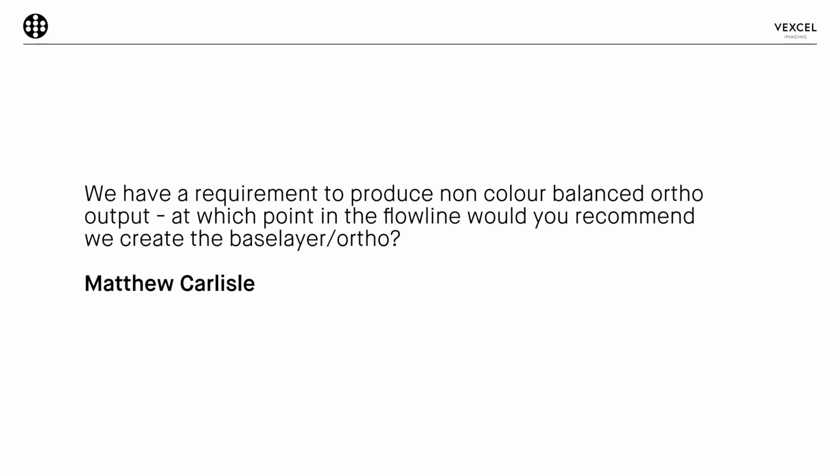So going for the first one, color balanced orthophoto, this is like the default path to continue in the software. And then for the non-color balanced orthophoto, we recommend that you take the radiometric settings from an early stage in the workflow before the color balancing, transfer that via the radiometry archive to this DSM stage, and from there start the processing of the orthophoto at high resolution using this radiometry where no color balancing has been applied.